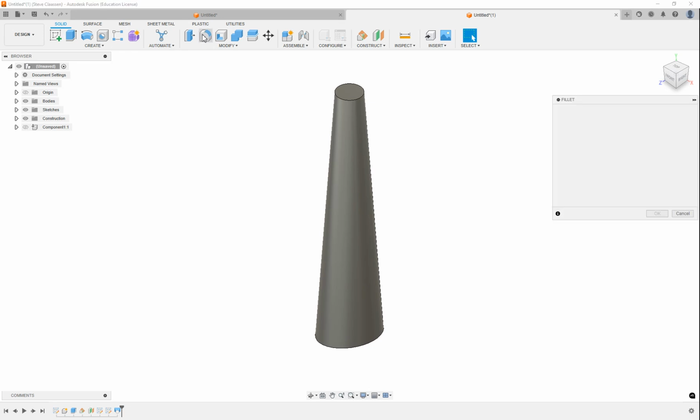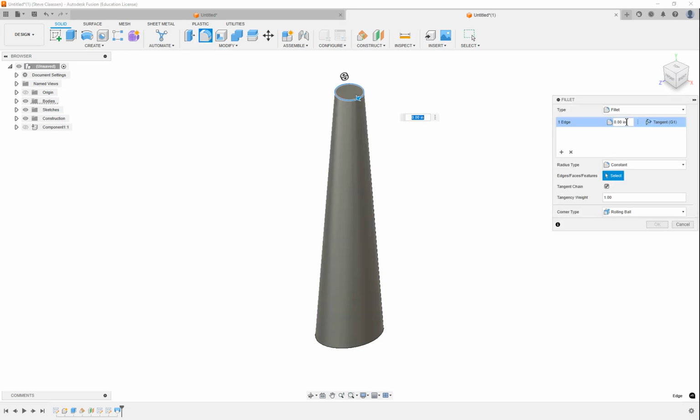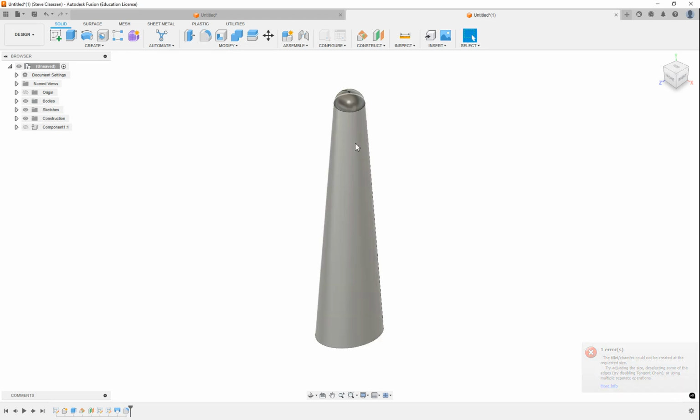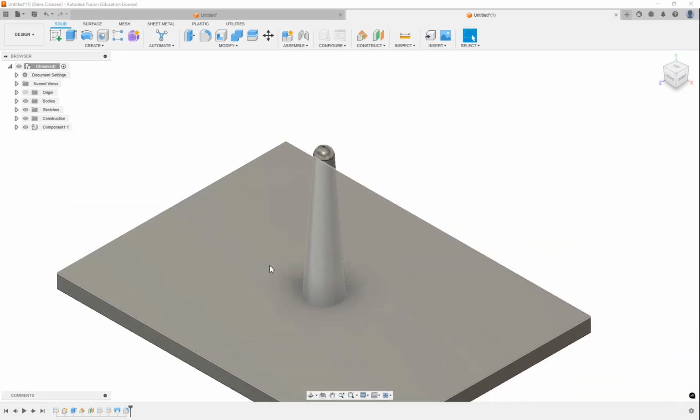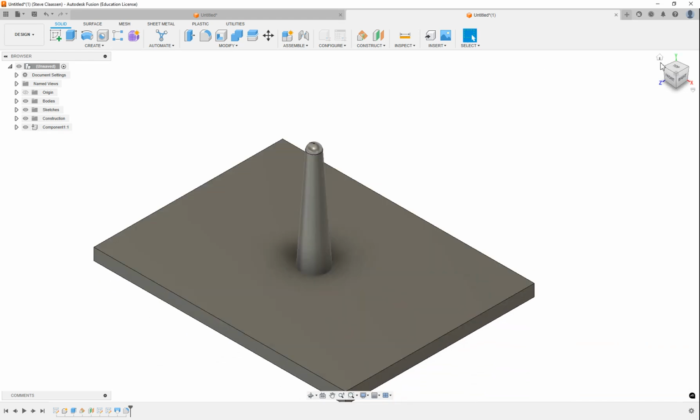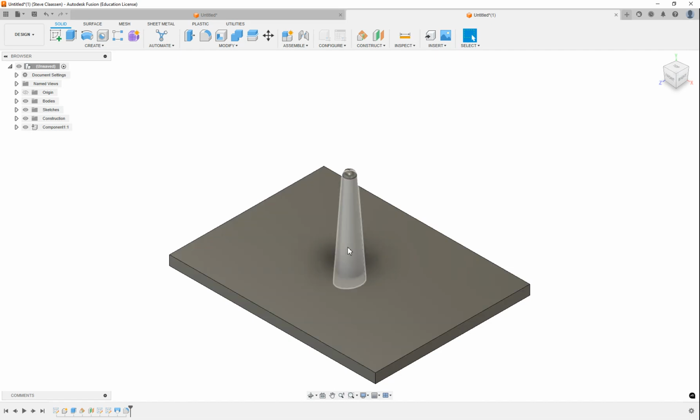And I'm just going to round the edge with a fillet at the moment. So I'll take that and go 3/8, 3/8. Okay, and there's a little bulb joint. And we are done with this part. So I'm going to turn back on the first component. There it is. Okay, now this is the top view, right? So there's our top. I want this on the bottom.